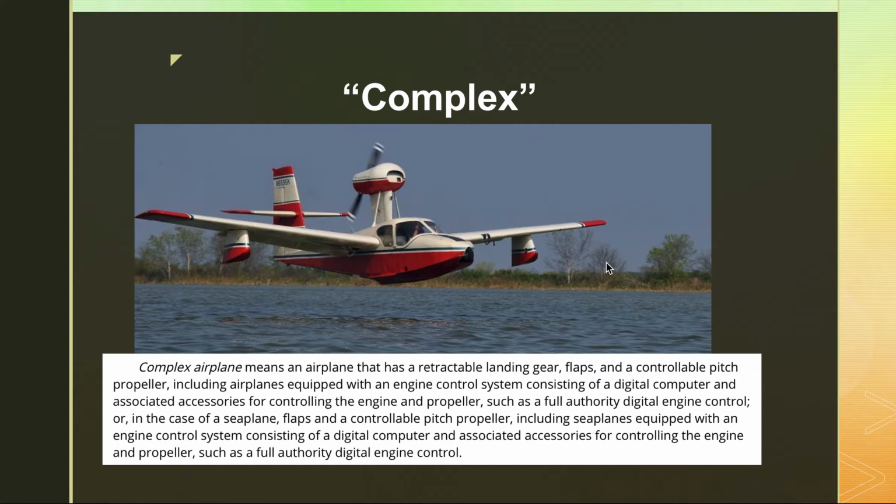So our LA-4 Lake Amphibian we're seeing here is a complex aircraft. It has flaps. They're actually hydraulically actuated. It has obviously landing gear because it's an amphibian aircraft. So this has main wheels that extend. They're hidden up inside the wing right here right now, so they've popped down and out, and then a nose wheel is inside the hull as well too. This does not have wheels on the pontoons because it has two mains that are pretty spread widely apart on the wings, and then the nose wheel.